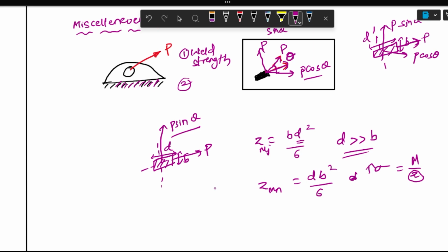Whenever you are going to design this lug plate, please keep in mind that for accidental loads, the load action will change abruptly. So what we have to do is place stiffeners. For example, if we place the stiffeners, then whenever the load coming onto the lug plate is divided into components, for example P sin theta, these are the stiffeners.